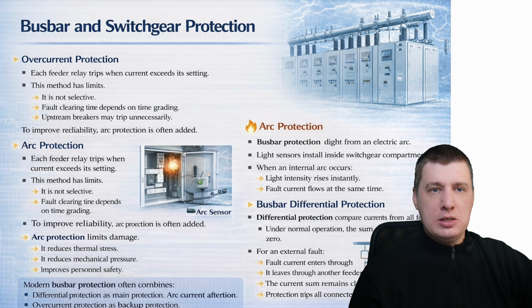Each feeder relay trips when the current exceeds its setting. This method has these limits. It's not selective and fault clearing depends on the time grading. And upstream breakers may trip unnecessarily.